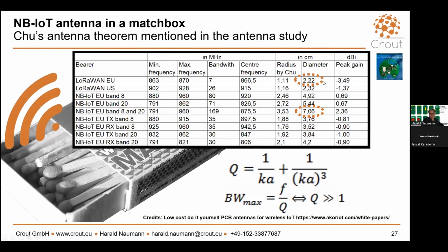Yes, and we mainly use monopole antennas in our designs. The antenna always has two parts: the dipole has two radiators, and the monopole has one radiator. And the second part is the PCB itself. It means the length of the PCB is related to the lowest frequency that you can transmit.